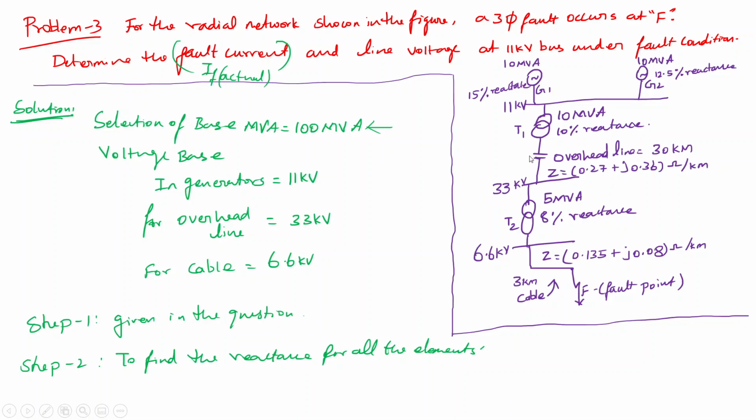If you are going to the high voltage side or the overhead line side, my voltage is 33 kV. So if I'm calculating anything after the higher voltage side of transformer one, I am already considering 33 as the base. So old divided by new for kV, whole square, will be the same: 33 divided by 33, whole square, is 1.